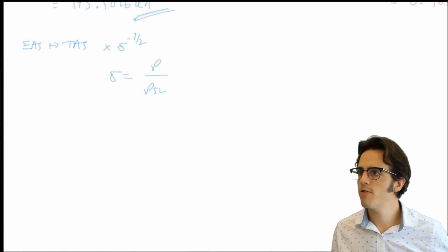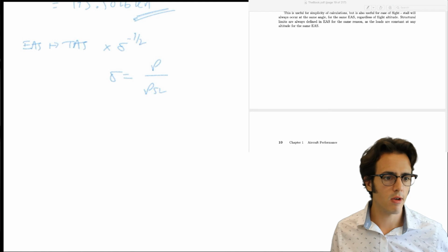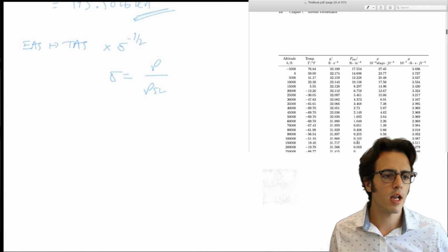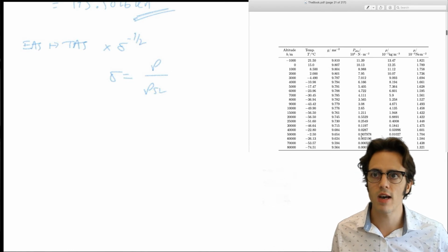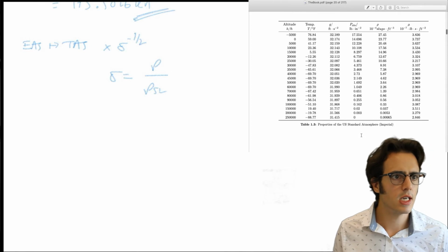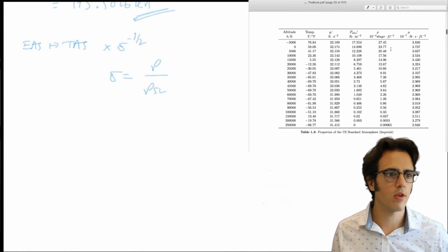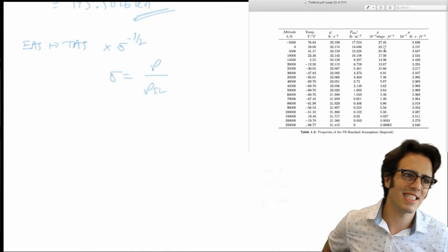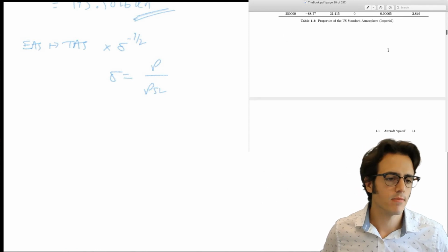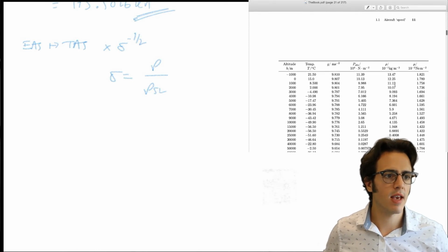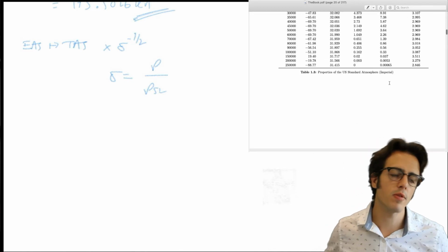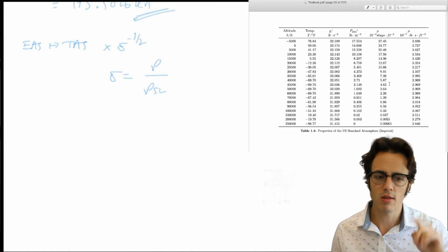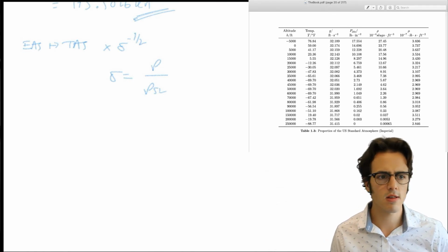If you follow the accompanying notes, which is what we were using for the course last year, you can use the values from either of these atmospheric tables. So we've got values of the US standard atmosphere, which I've got in the old units: take these, multiply them by 10 to the minus 4, and that's density in slugs per cubic foot. Alternatively, you can take these, divide them by 10, and this gives us density in kilograms per meter cubed. If you go through and do these values, you will end up with a value for sigma that's slightly different.